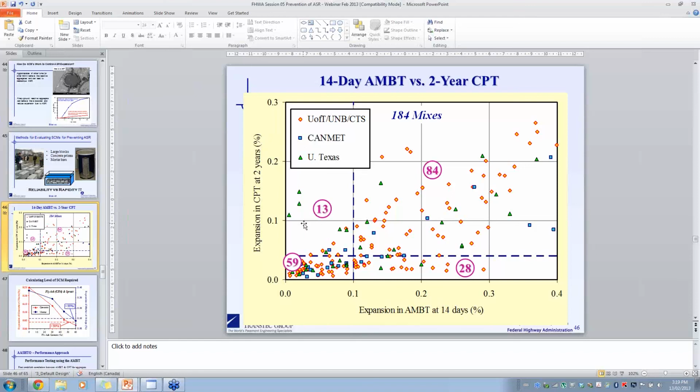Generally, I would say that with that particular case, although the impact of ASR has been huge in terms of managing the structure, in terms of jamming turbines, closing gates, it's been a disaster in terms of trying to operate the structure. If you take cores out of a structure, the changes in mechanical properties, certainly in terms of compressive strength, are not really that significant.